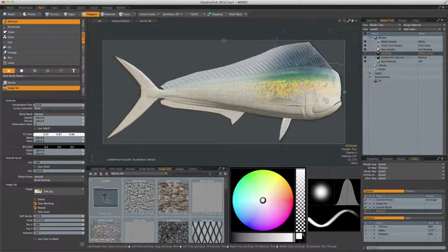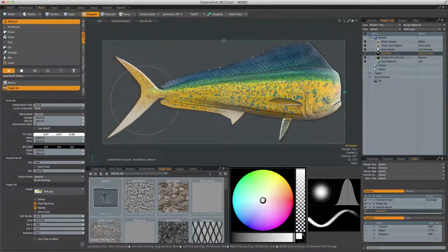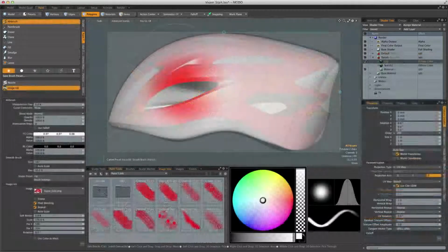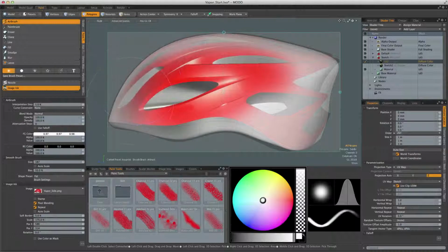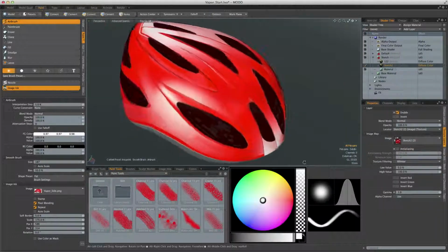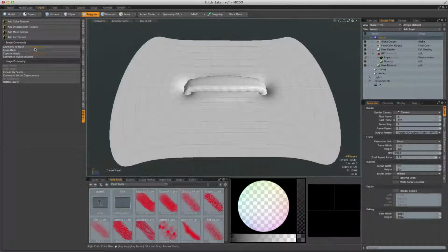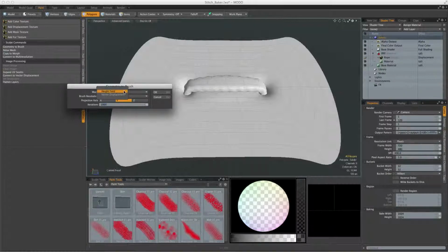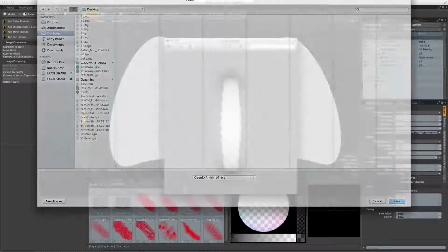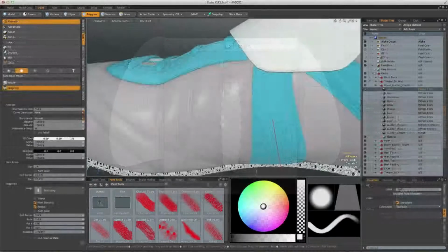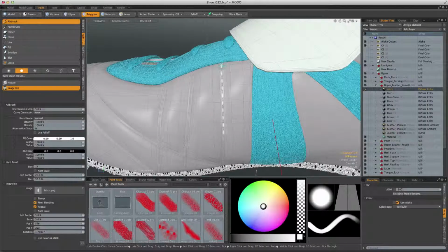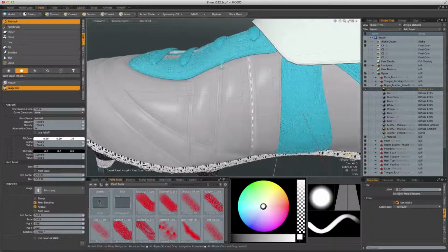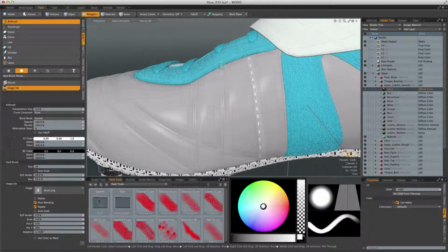This allows you to paint an image onto a surface, either using the colours of the image or alternatively using the image as a mask. It's incredibly useful for applying 2D sketches to a 3D volume that can then act as a guide for future modelling. Because MODO's painting system is so integrated with the rest of MODO, you're also able to generate height fields from geometry and then utilise them as a brush. It's a great way of producing accurate displacement or bump maps of difficult to reproduce geometric patterns or objects.